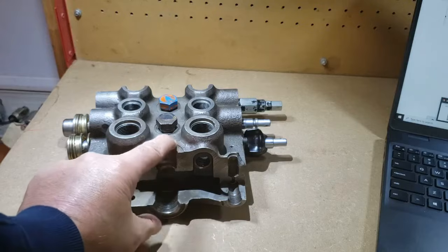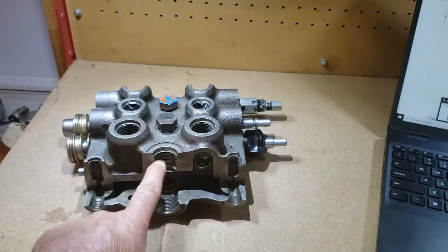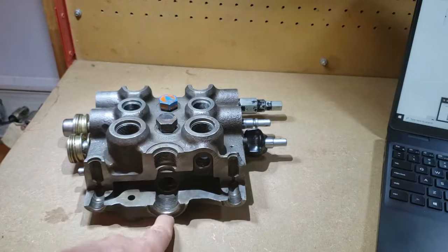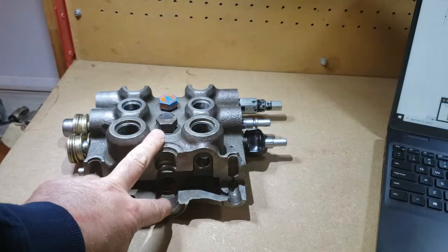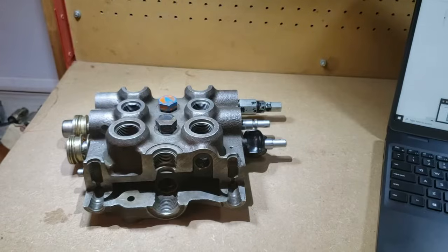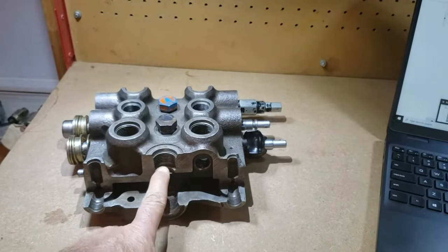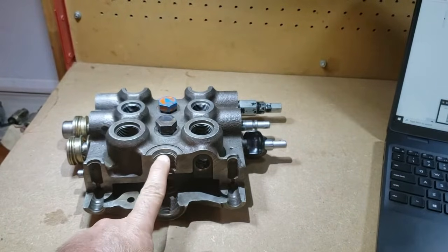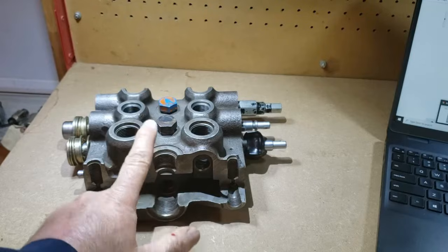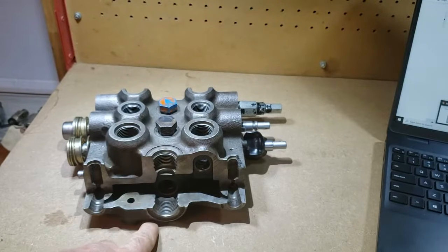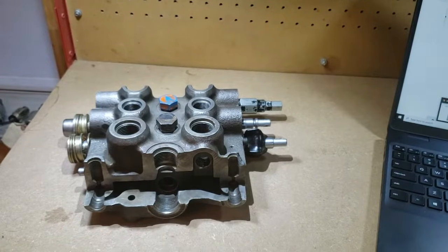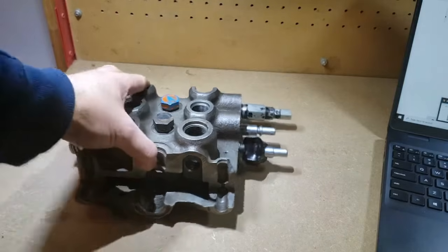Depends what frame of machine. Sometimes they put a plug here and return the oil out here. Sometimes they put a plug here and return the oil out here. And on some machines, I've also seen that they will have the oil heading for the cooler at one of these returns, and then they'll have a cooler bypass valve in the other, which if the restriction through the cooler is too great, it'll bypass the cooler and just dump in upstream of the full flow filter on the way back to tank. But that's the return end.